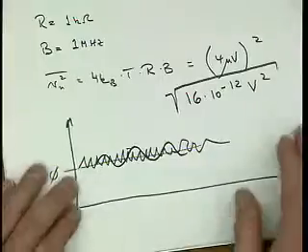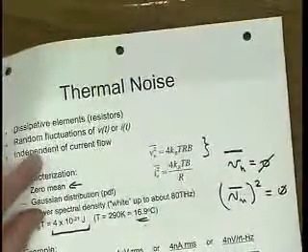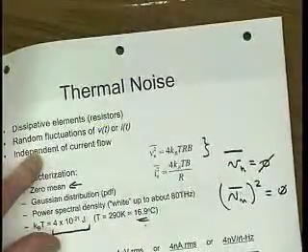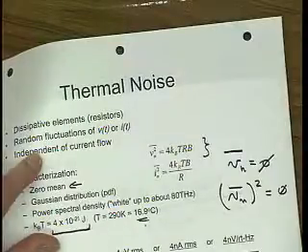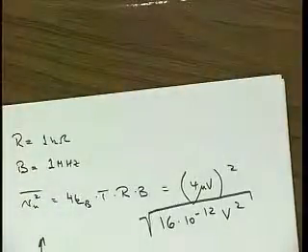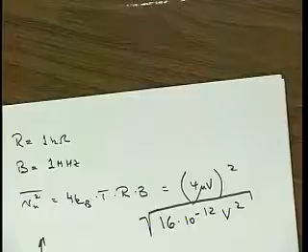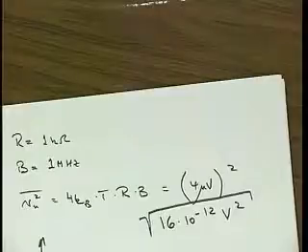All right, so that then would be one interpretation of this 4 microvolts, and that's why I usually say it's 4 microvolts RMS, because the noise power is the same as the power from a sinusoid with 4 microvolts RMS amplitude. That's really what this means. Okay, so apparently 4 microvolts, right? If I build a sensor that puts out nanovolts or so, then it's probably a problem.